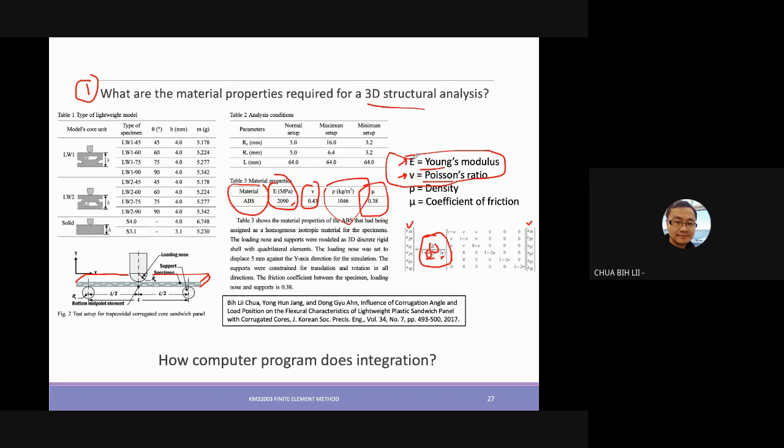But for sure, in reality there are a lot of other defects and other things that come in. So if you can do some testing of the material being used, that would be better, instead of taking it directly from the books or the appendix in the textbooks. Because for those appendix values, you may not know the conditions of the material. It may be slightly different in terms of the process, which gives different characteristics of the Young modulus as well as the Poisson ratios.